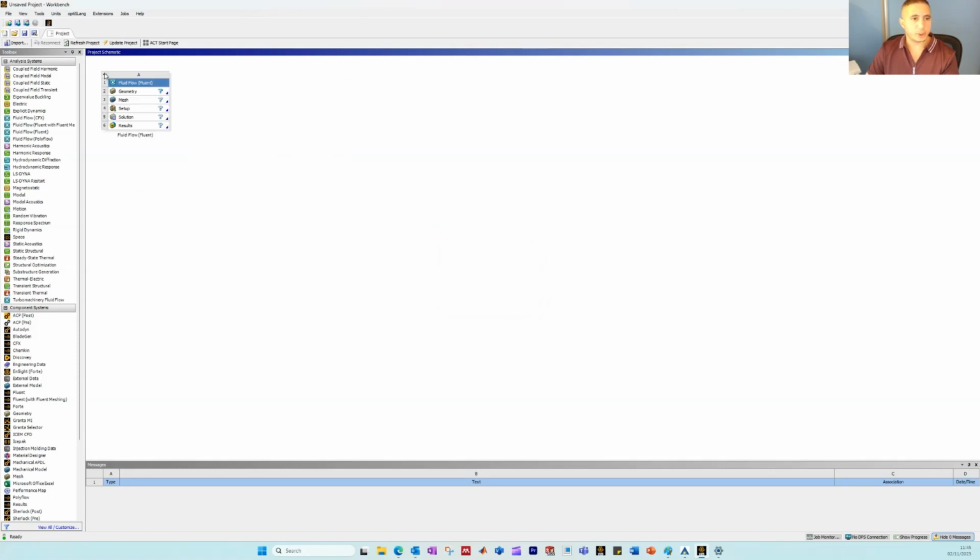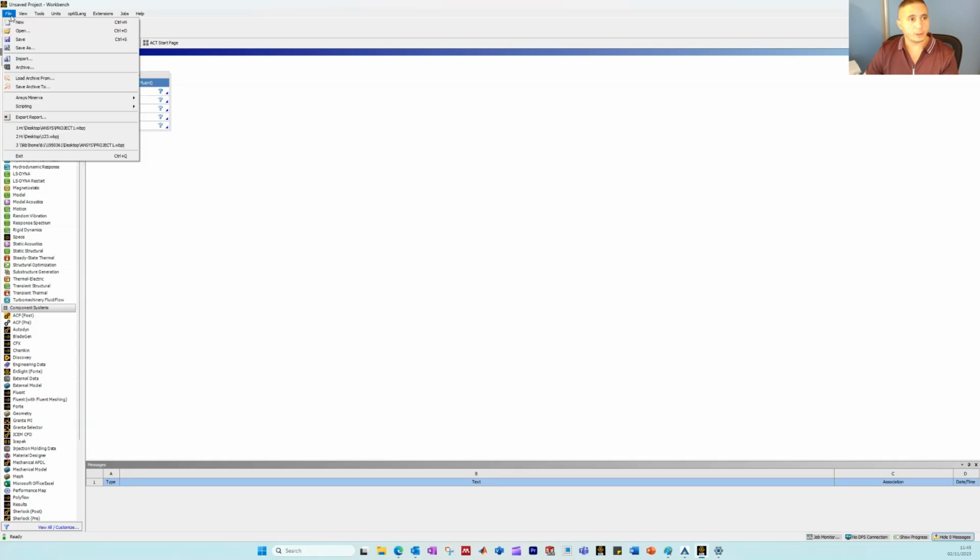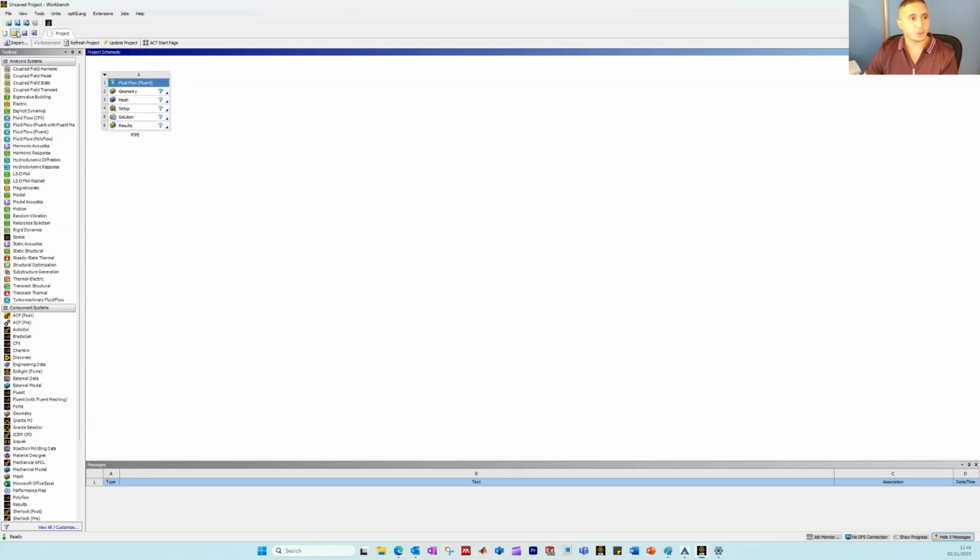So as I said, I'm going to work with this system now. First thing you do, you rename the system that you will be working on. Just click in there, rename, then I'm going to call this pipe. The first thing you're going to do now is to save this project. So you go to File, Save or Save As, or just click on this Save Project. Don't forget, don't click on Save Analysis, the Ansys one here. You just click on the Save Project.